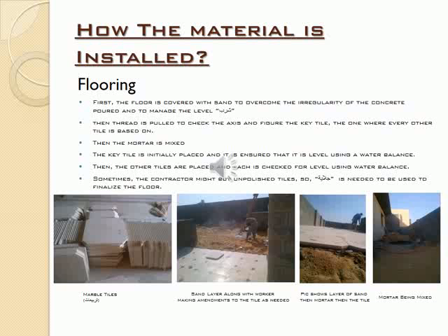After the key tile is placed, we start placing the other tiles next to it, and we use a water balance to manage the horizontality and make sure that every tile is level and every tile is right next to each other without being shifted up and down, and they are at the right place.